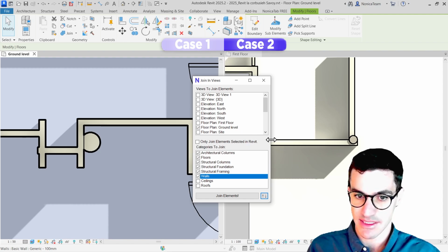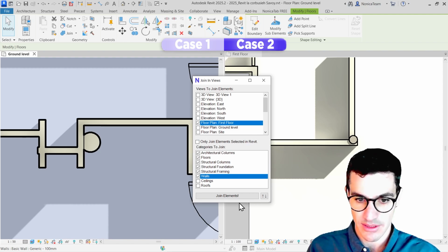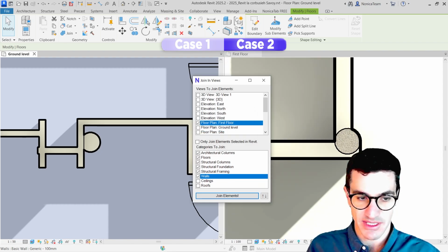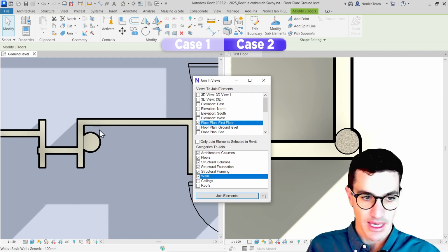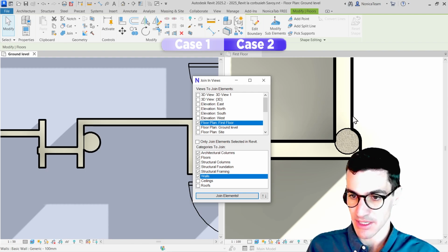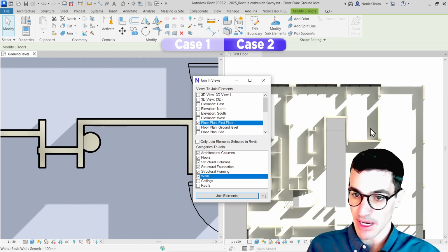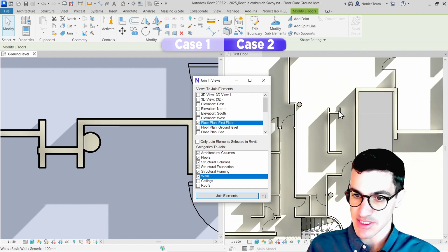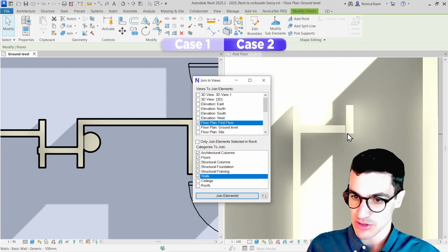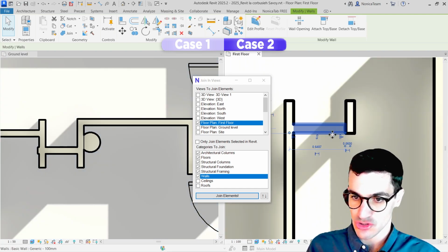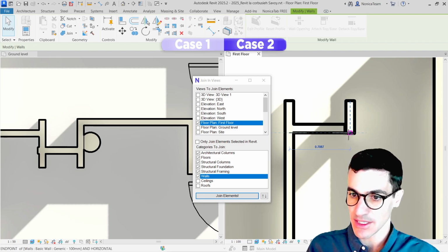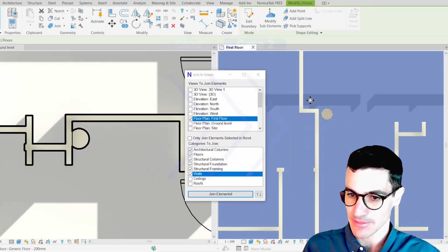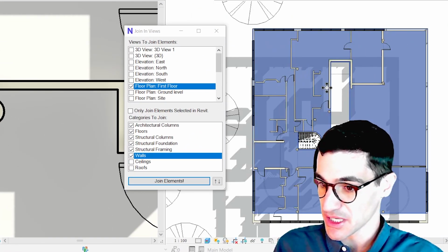Great. So let's just mark the floor plan I want, and then let's run. We see now that the join with the column is different. As I set the priority, we see that now the column per surface is safe, and we still have the clear outline. But we see that, for example, there are some walls over here that have not joined. If this happens to you, it may be because the walls do not actually intersect. So if you just enlarge them a little bit, this will do the work. Great, so I think it's pretty clear.